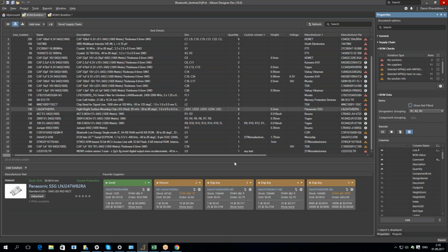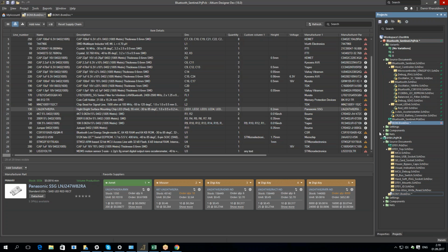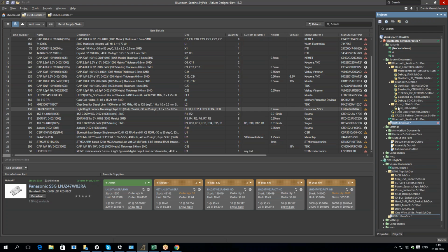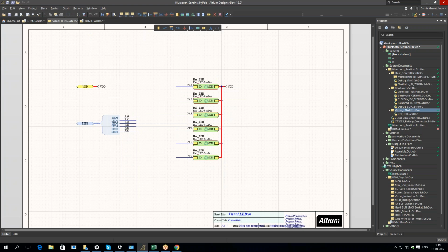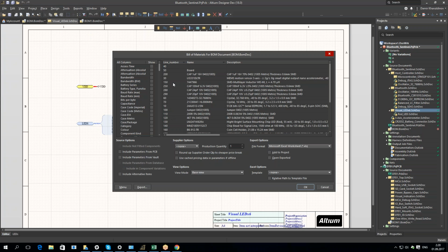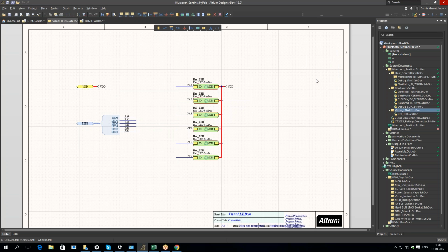If you have your ActiveBOM document in a design, it becomes the source of all your BOMs. So even if you run this report from the schematic, when the schematic document is open, the report will show data from the ActiveBOM document. You always see your master BOM. No longer differences, and you don't need to use output jobs to run your BOM as in previous versions.